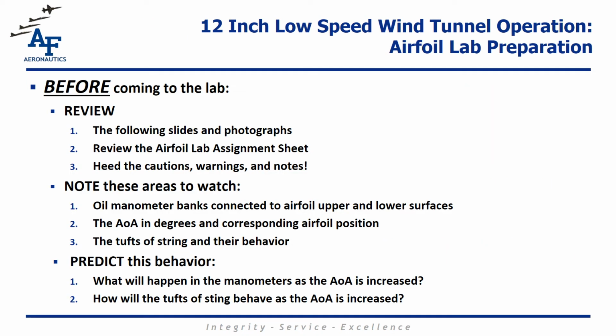Before you come to the lab, please ensure you review the rest of this slide deck. Review the cautions, warnings, and notes. As a team, you'll monitor the manometer oil bank, the behavior of the tufts of string, and the angle of attack you'll set on the wind tunnel airfoil. Think about what will happen to those columns of oil as we increase angle of attack, or how the tufts of string may behave as we increase angles of attack.